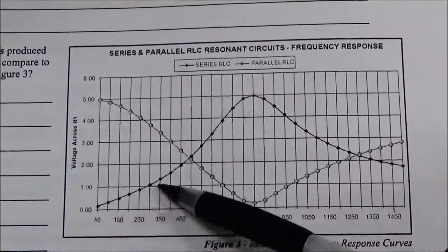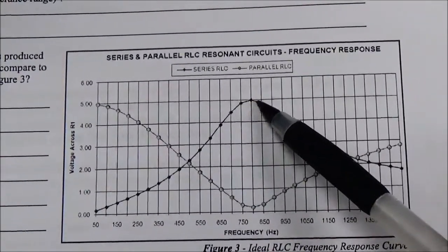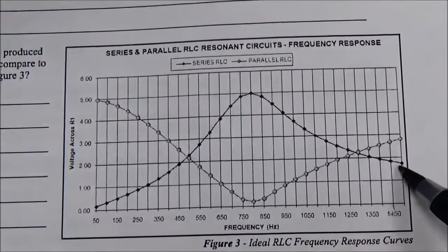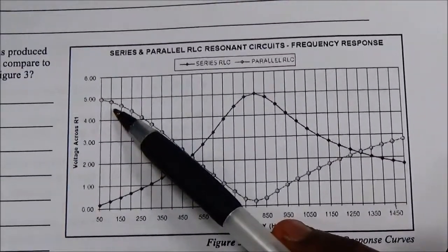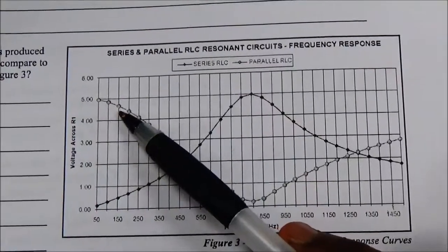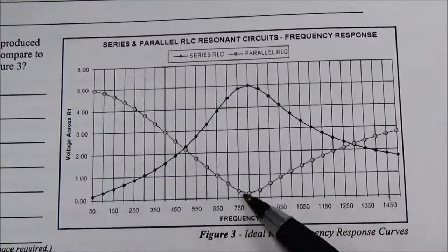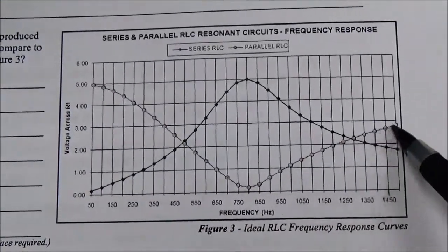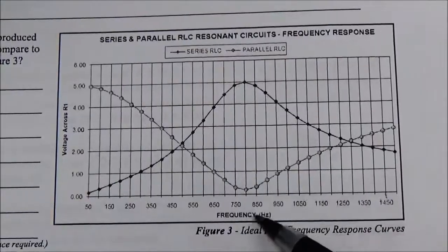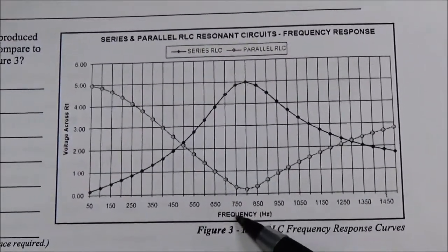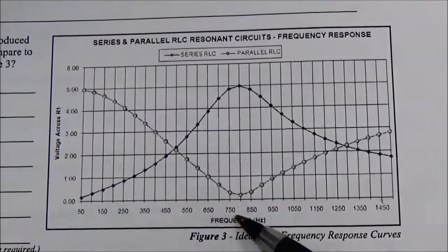For series resonance, the values keep increasing up to a point and it starts decreasing. You get a bell curve. An inverted bell curve is obtained when you connect the capacitor and inductor in parallel. The values keep decreasing up to a point and start increasing. You would see practically at what frequency this happens, and I shall teach you in theory how to get this resonant frequency.